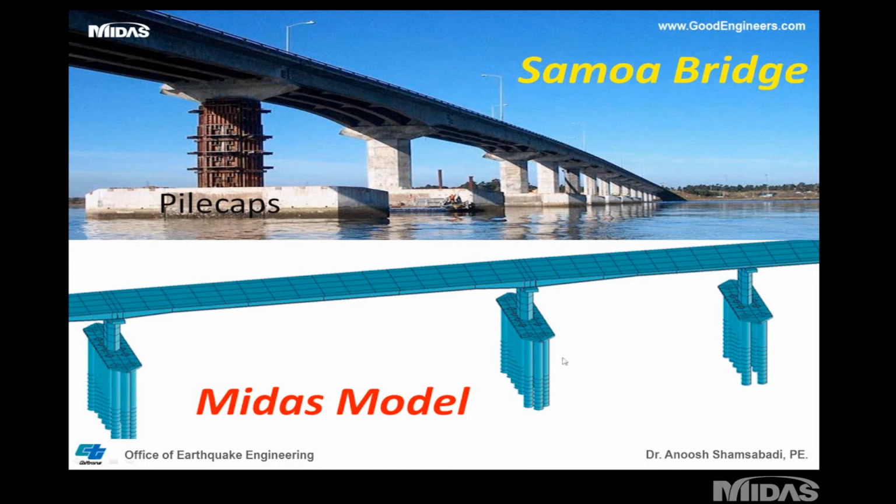For this type of structure, the correct modeling of the pile cap, correct dimension, correct mass of the pile cap is extremely important because it's a dynamic system and mass comes into play. So it is very important to make sure you include the pile cap mass and, if you can, the pile foundation as part of your global system, so all the mass participation will come as real as possible.